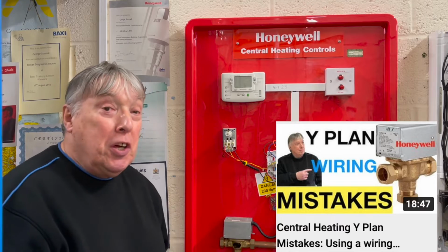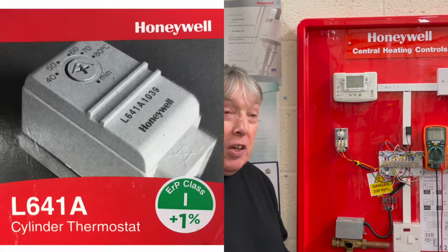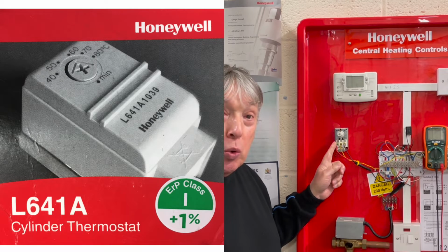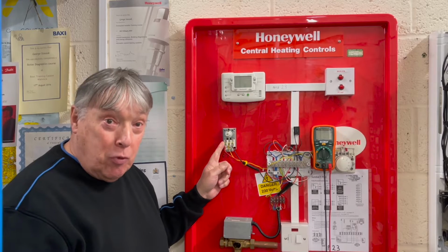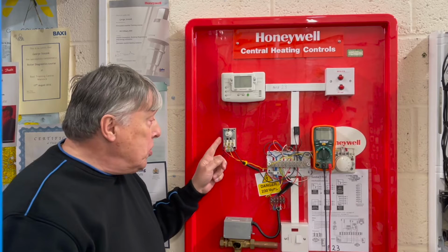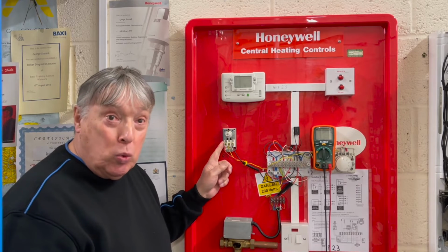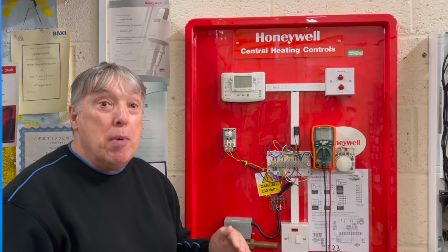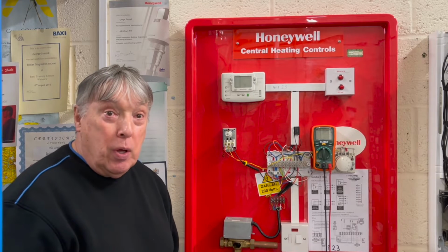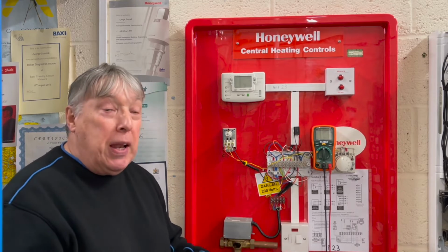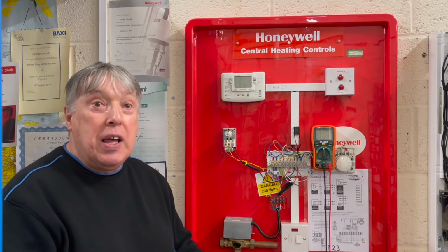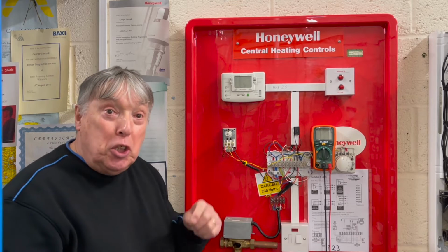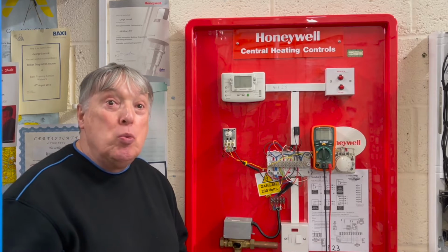What engineers don't realize is this thermostat controls the heating. It really does, because whilst this is in hot water mode, you either get no heating or at most 50%. Engineers go all over the planet looking at diverter valves, this, that and the other, and that's the one that's faulty. So let me show you how it's done, and we'll zoom in.